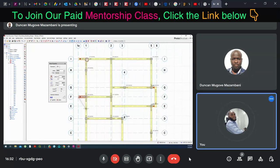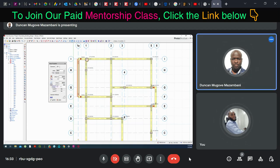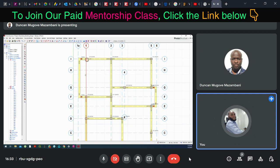Okay, that's fine. Then join it together, then change the option to the first option. Use the first option, and update. That's fine. Now escape and remove the beam inside and the column inside too. Take it off. That's fine, and that one too. Now let's see our 3D view.